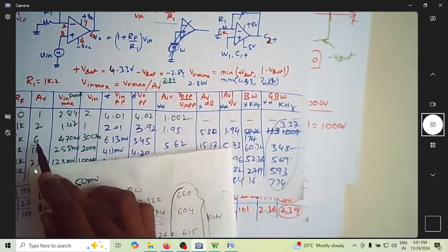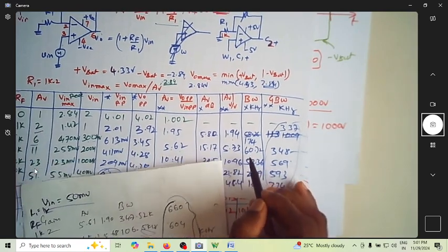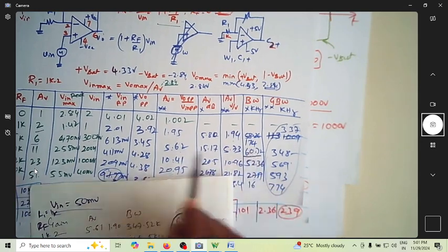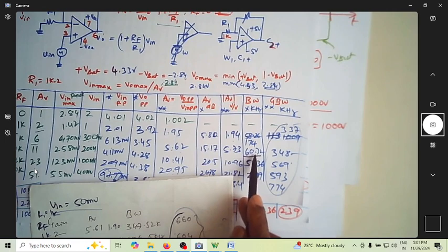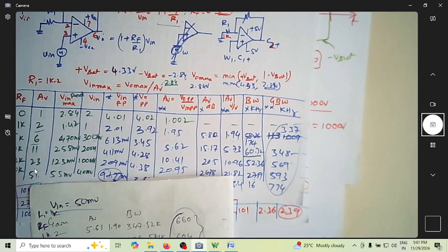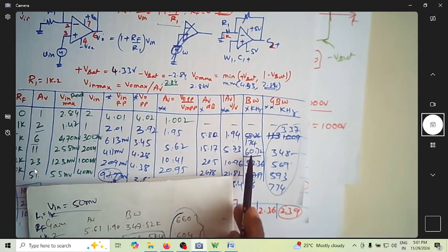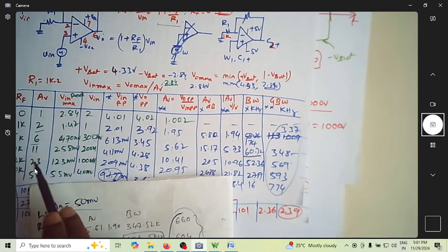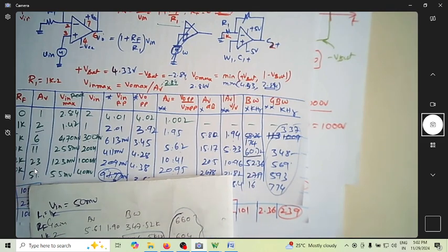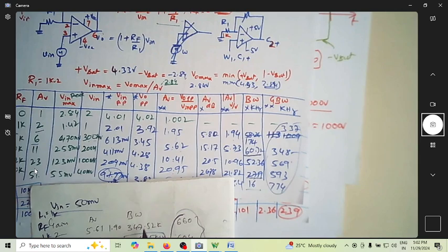Here for a gain of 6 you had a bandwidth of 60.32 kilohertz, and now you're getting a bandwidth of 106 kilohertz. So where is 60, where is 106? For a gain of 11, I had a bandwidth of 50.8 kilohertz, this was 52, and here you can see a bandwidth of 27 kilohertz. I'm having it as 30. So here it is fine, especially for lesser gains. For lesser gains, if the amplitude is more, it takes longer.